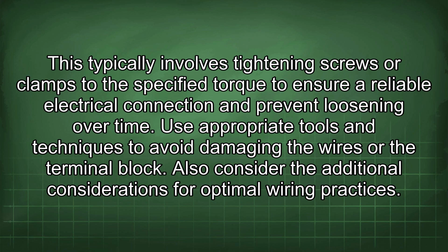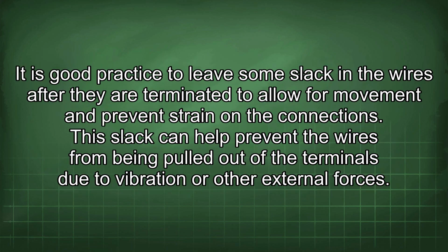Also consider the additional considerations for optimal wiring practices. It is good practice to leave some slack in the wires after they are terminated to allow for movement and prevent strain on the connections. This slack can help prevent the wires from being pulled out of the terminals due to vibration or other external forces.